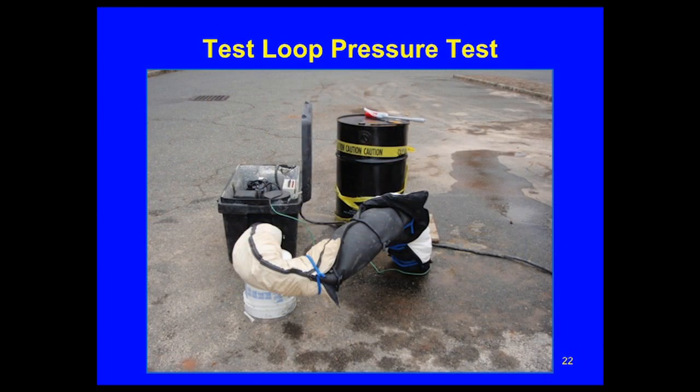After that borehole is put in, we run a conventional test to evaluate the Earth's thermal conductivity. The test is pretty simple. This looks like a magic black box, but all it is, is a pump and a heat source. So we pump water at a constant and continuous rate for 48 hours, and you apply a constant heat source.